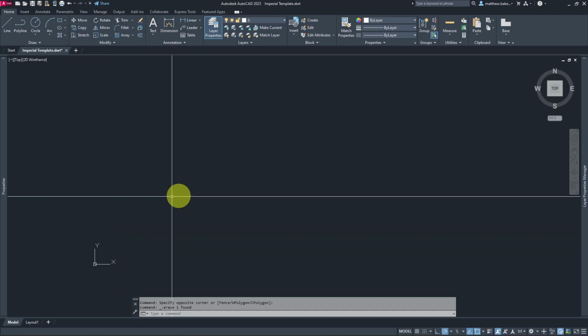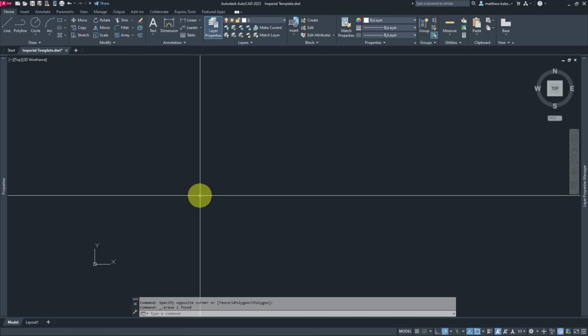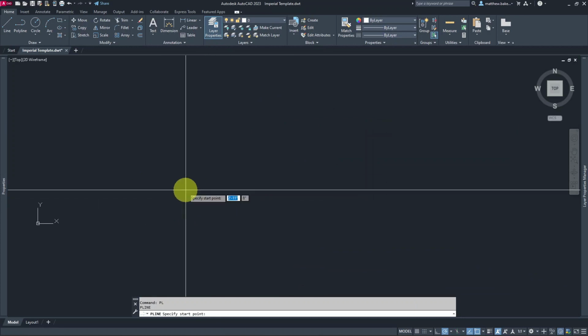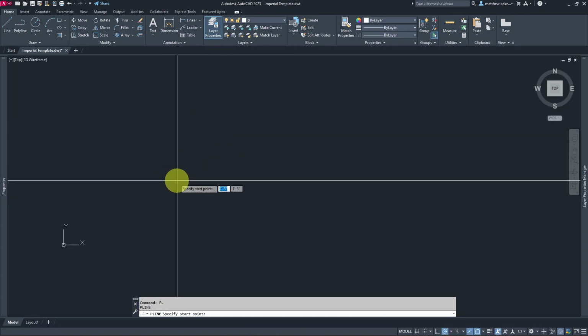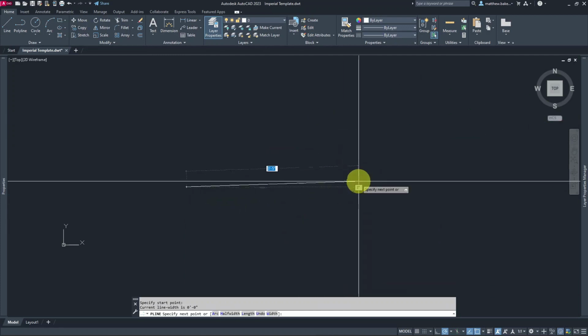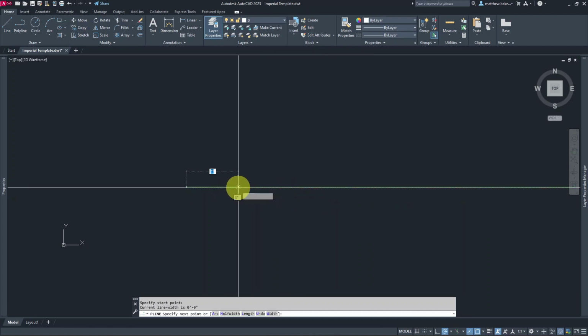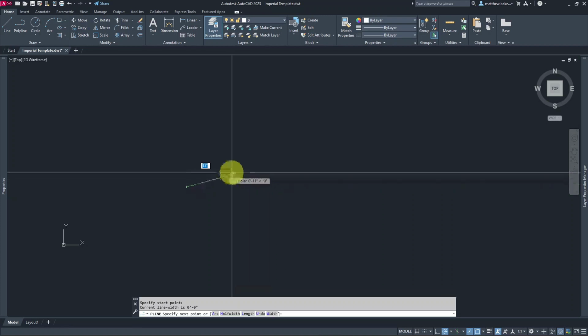Generally, you don't need to use coordinates for input. You could do what's called direct distance entry. So direct distance entry is just, again, polyline. I prefer polylines over line just because they're a little bit neater. With more line segments, it stays together as one object, whereas with standard line, each line becomes its own object. So that can get messy later on.